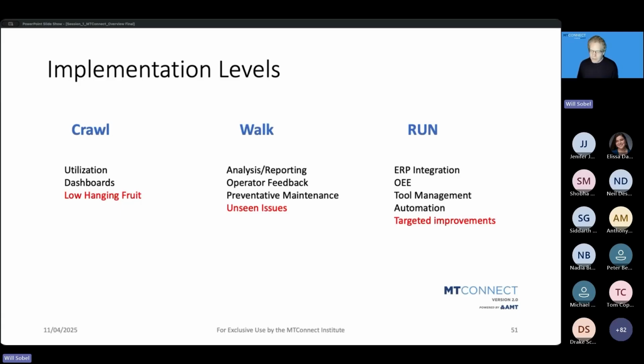Next stage is use-based maintenance, where you schedule maintenance based on, for example, spindle hours. So how long has this spindle been spinning? Then let's do it every, let's say, couple hundred hours. Next, beyond preventative, you can get into predictive maintenance.